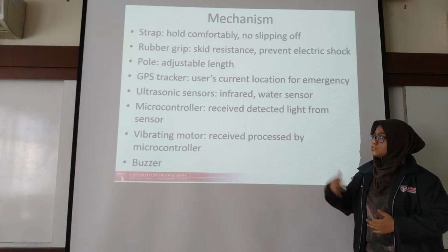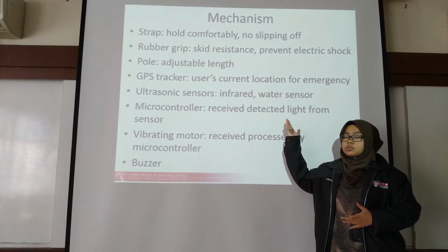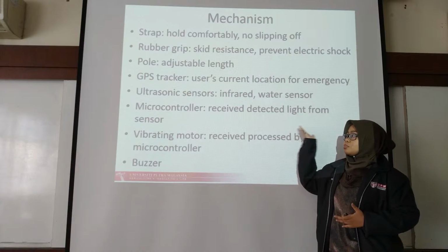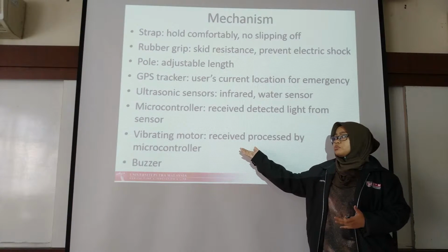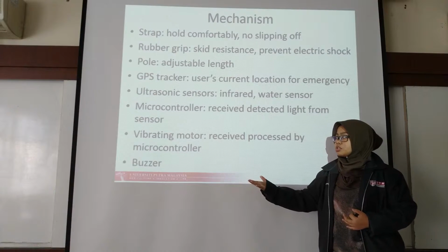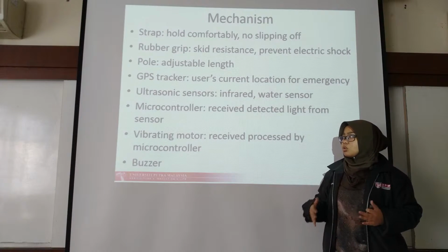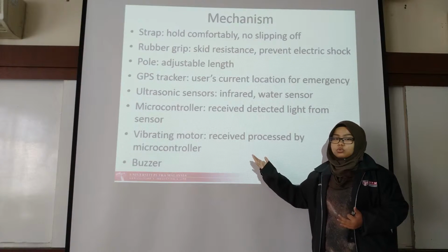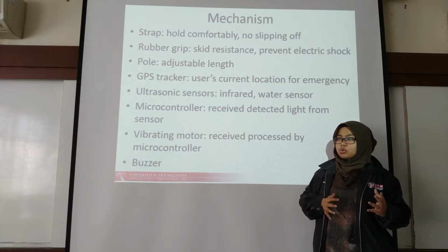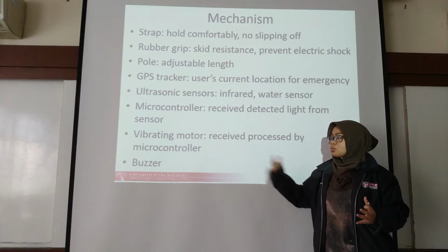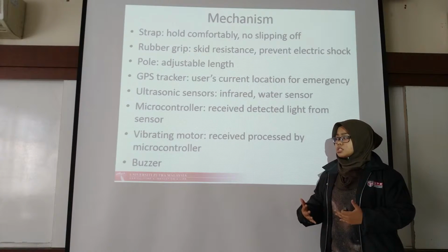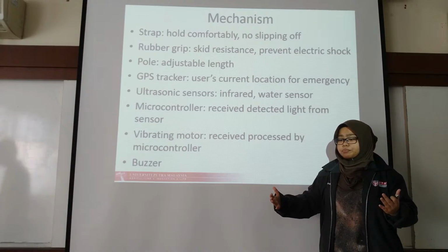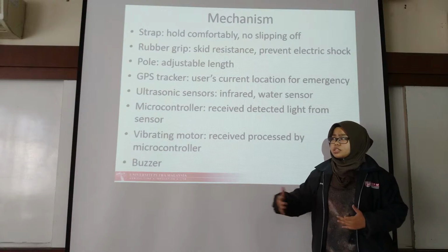For the microcontroller, we use Arduino. The sensors detect the input and send it to the microcontroller to be processed, and then the processed input is sent to either the vibrating motor or the buzzer to produce an output, either vibrational motion or an auditory response. The vibrating motor will vibrate more frequently as the object becomes closer, while the buzzer will make a louder sound as it gets closer, to give the user a sense of the distance between the user and the obstacle.